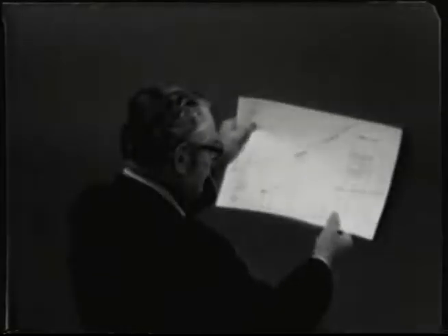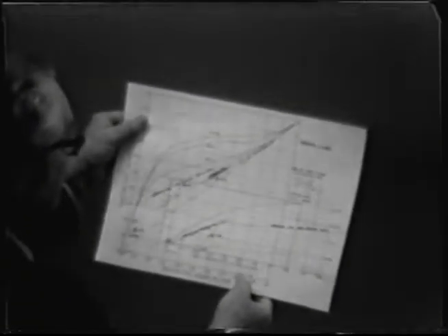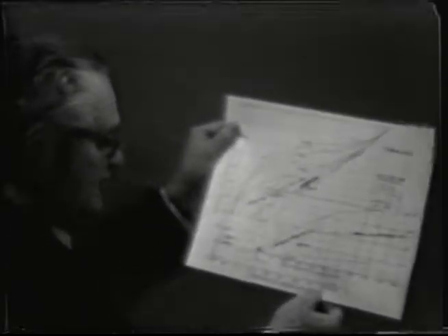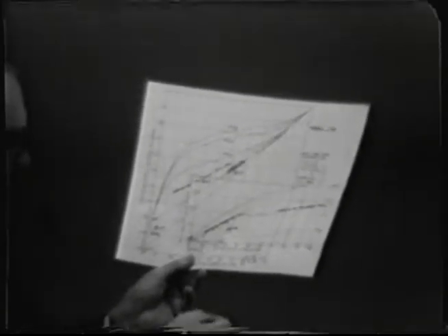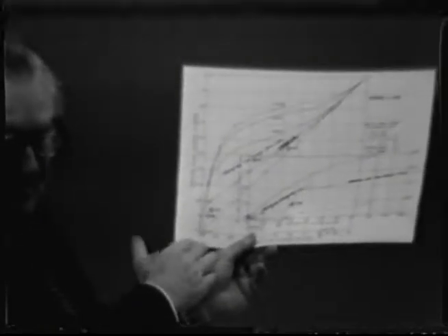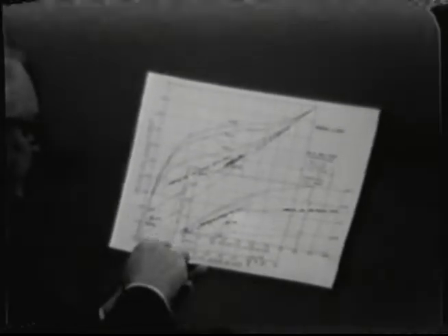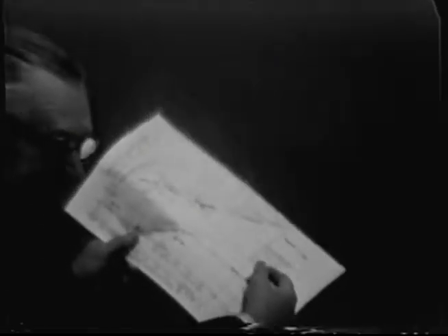So, using our usual procedure, we've located on the chart here the composition of the top distillate, which is 0.856 mole fraction, the side stream product, which is about 0.81 mole fraction, and of course bottoms is so low that it's impossible to locate on the main chart. So I've attempted to do it on this little expanded chart, and it's still so small that it's not very realistically solved by this kind of graph.